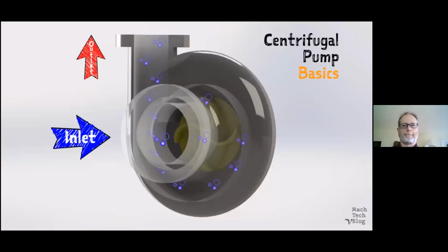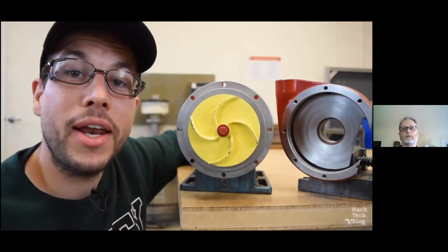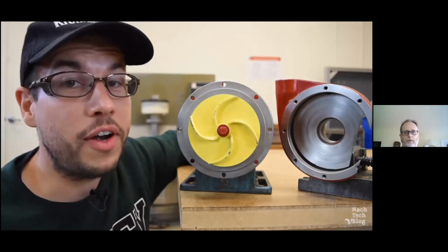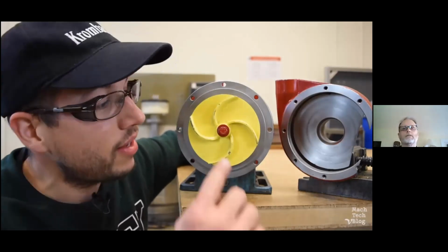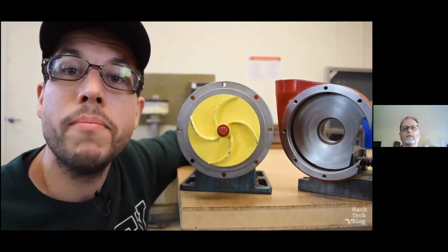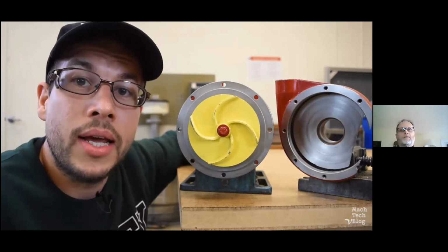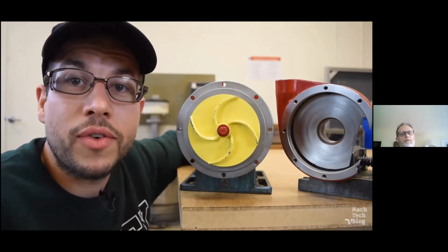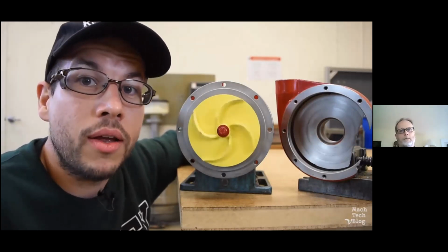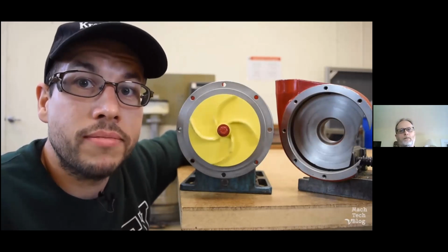From the impeller, the fluid is released into the chamber of the volute casing and directed around to the discharge outlet, and ultimately into the system. Let me take a minute to set the record straight. A very, very common misconception is that these curved vanes help to move fluid by cupping it and pushing it through the pump. So then the correct direction of rotation for this impeller would be clockwise, right?